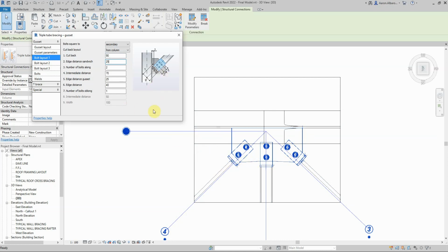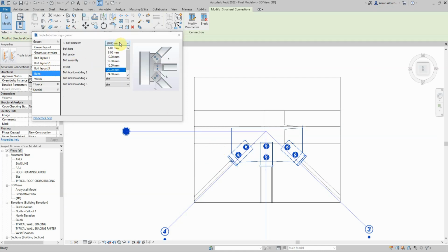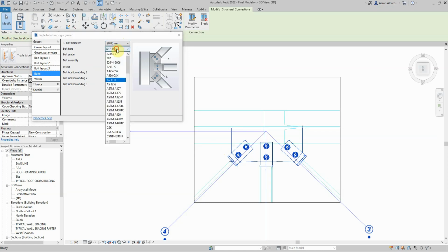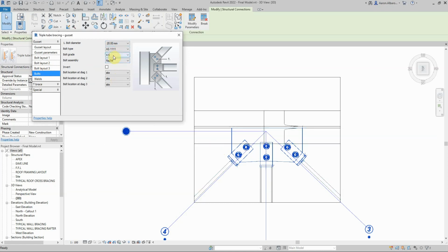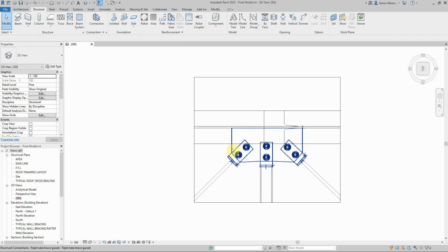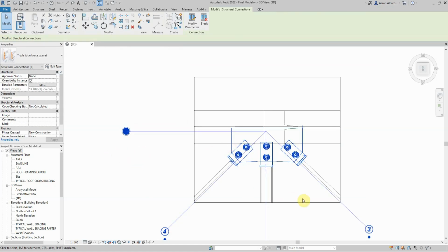So this is it really, what we can utilize from this connection. We can't do anything else. All we need to do now is just make sure that we choose the right bolts. We've got these bolts we're going to choose as we agreed, high strength bolts, high grade, snug type with 2 washers we agreed we're going to use, and that's it, done. 20mm bolts. Close that.